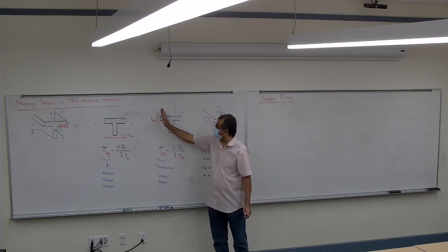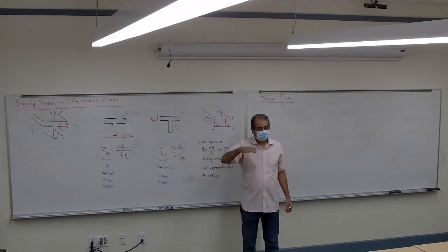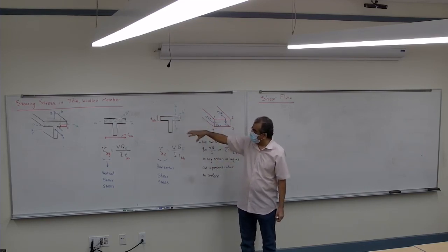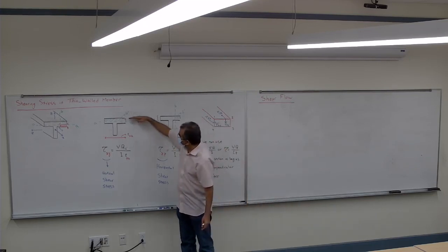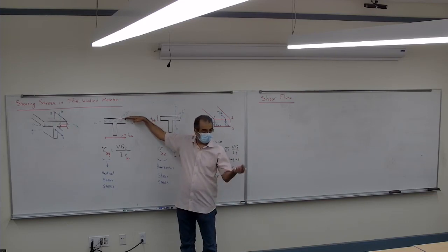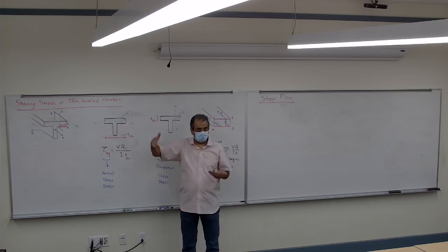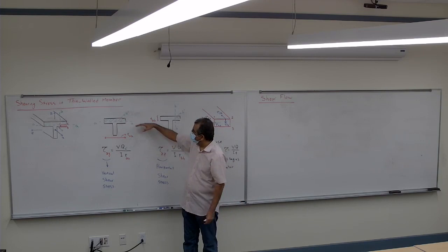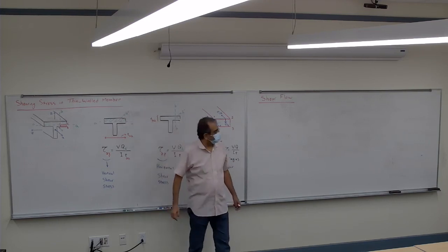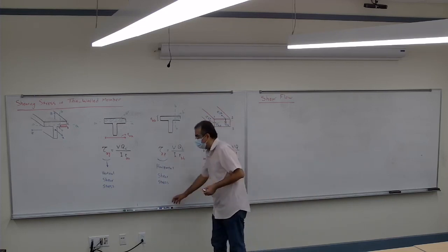The same is here. If I cut it very close to that edge, this small cube is very small, and then it becomes larger and larger. So if you look at this problem, you'll see that it depends where I'm going to cut it. The same here, if the AA is at the very top edge, the area is going to be 0. If I keep moving down and down, the area becomes larger and larger, so the shear stress becomes larger and larger. So it's very dependent on where I'm going to cut it. This is where the idea comes, mostly visually, to see how things change.